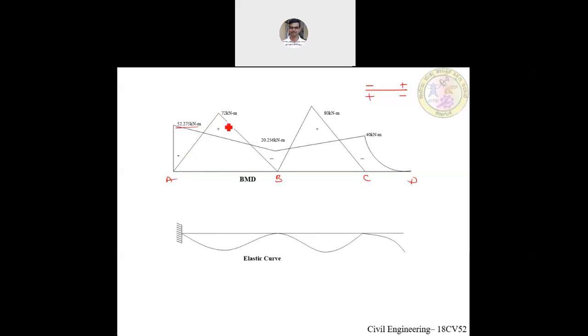And we are going to superimpose the simple bending moment, as both spans AB and BC are applied with a concentrated load. The variation of the simple bending moment would be a triangle, and we are superimposing the negative bending moment and the positive bending moment, and this portion will get nullified. And here also this portion gets nullified, and this portion will have a negative bending moment. This is positive, negative, it is hogging, and here we have sagging, and this portion will have continuous hogging. That is, for a cantilever span, because of the uniformly distributed load in the downward direction, the beam would go into hog.